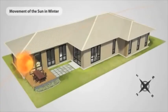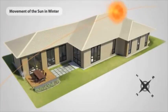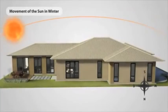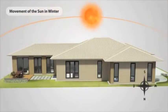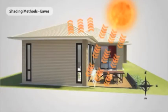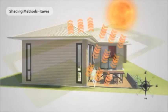In winter, the sun is lower in the sky, which means the sun can penetrate the windows, creating heat gain and reducing the need for artificial heating. This view shows the winter sun shining through the windows. Shading methods are important because you need to maximize heat gain in the winter and increase shade in the summer. A simple way of maximizing efficiency is to create eaves for your house.